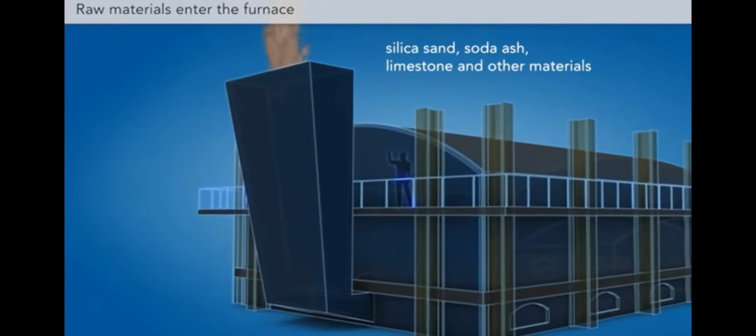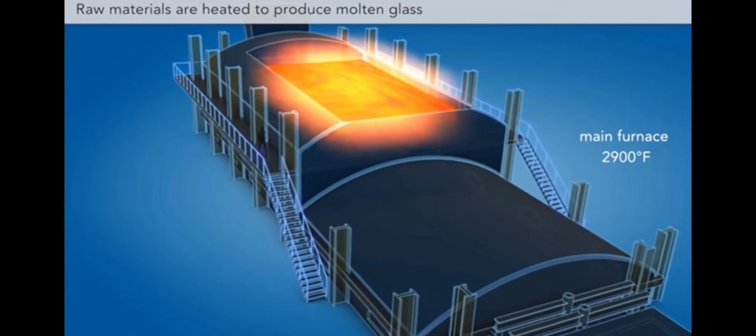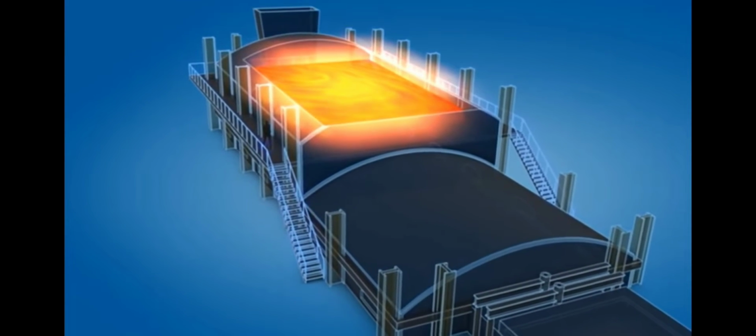Okay, now I'm going to explain the method of the Pilkington process. There are 6 stages in total. The first stage is the melting and refining process. Processes like melting, refining, and homogenizing take place simultaneously in the furnace and last about 50 hours.